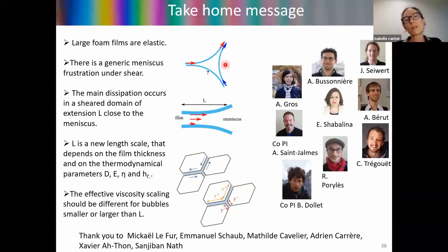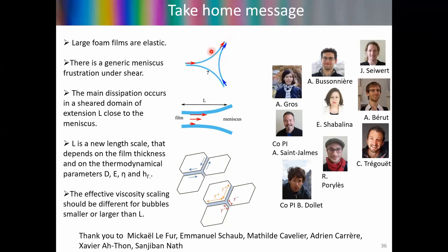So to answer more precisely the question, there is no need to neglect or take into account the pressure here, because everything happens a little bit outside the meniscus, and when you reach the meniscus, you can flow easily. So the Laplace pressure is important, but does not influence the motion we are dealing with, which is a tangential question, whereas the curvature is more important for the normal forces.